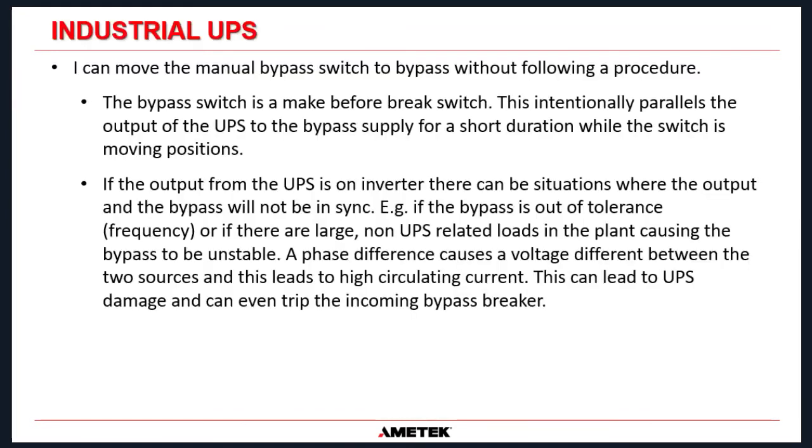The next misconception: I can move the manual bypass switch to bypass without following a procedure. You can, but you may have a bad day if you do that. Because remember, the bypass switch is a make before break switch. Well, it should be a make before break switch. And this intentionally parallels the outputs of the UPS to the bypass supply for a very short duration of time while the switch is moving from normal to bypass to low position.